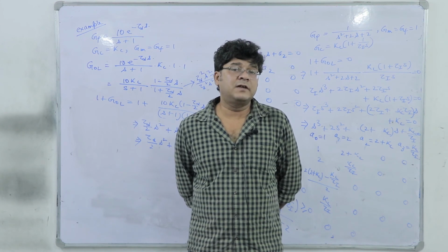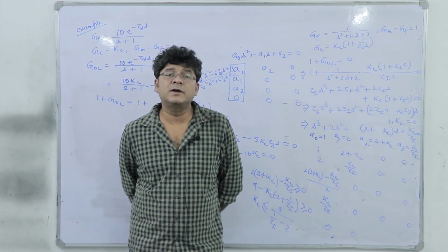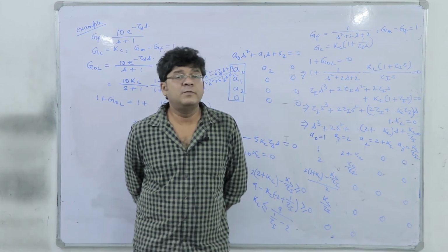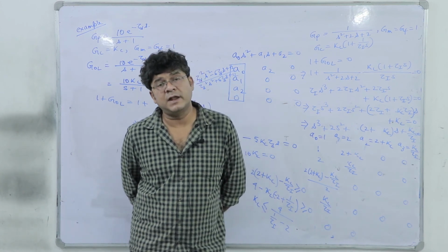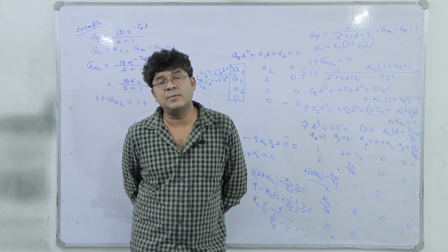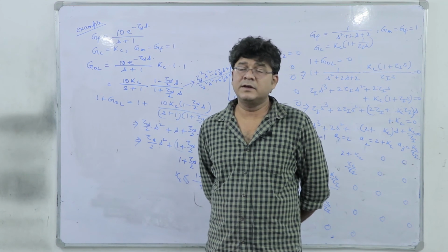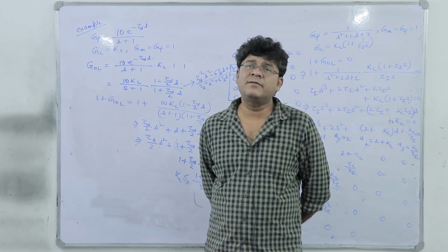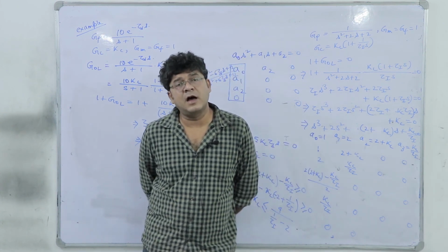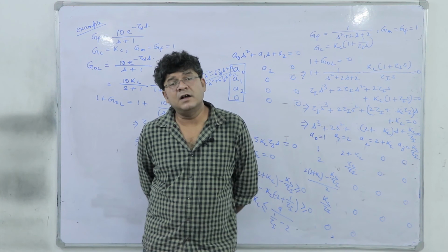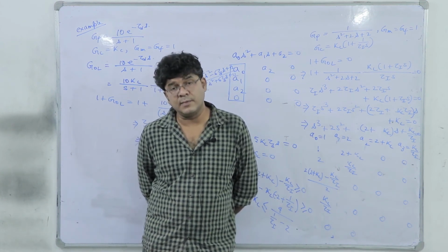And from this frequency response analysis, we can reveal some of the very important features of the transfer function, which we cannot decode using the standard monotonic input like step or pulse or ramp or impulse, right. So, that is why the frequency response analysis is very important. And you may be thinking why we have to decode this transfer function. See, most of the process systems are highly complicated and non-ideal. So, there we have to determine its working transfer function through experiment, right, not by modeling.